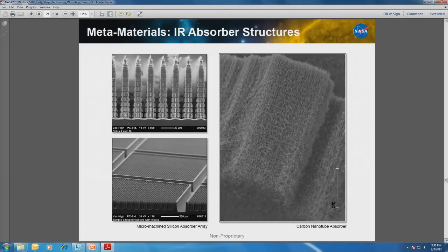This is a micromachined silicon object that has been coated. And it needed to slip in behind a detector and terminate light that would have otherwise been reflected. And it needed to fit in a very small region, but it didn't need to be incredibly black. It needed to be greater blackness and absorptance higher than 0.9. And it's probably like at the low end of the band, it's probably like not 0.95, and in the optical, it actually is quite good. But where it's actually being used is around 0.95 or better. So that's another place where you can play that kind of game.